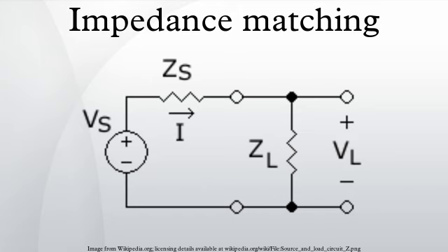Given a source with a fixed voltage and fixed source impedance, the maximum power theorem says this is the only way to extract the maximum power from the source. Devices intended to present an apparent load of Z_load equals Z_line, to avoid echoes. Given a transmission line source with a fixed source impedance, this reflectionless impedance matching at the end of the transmission line is the only way to avoid reflecting echoes back to the transmission line.